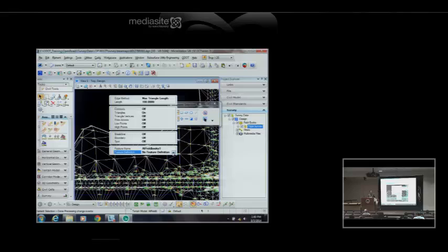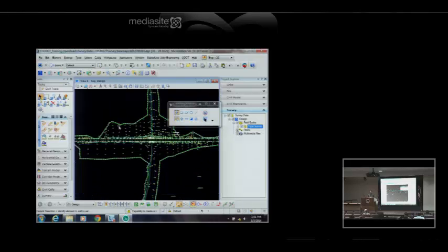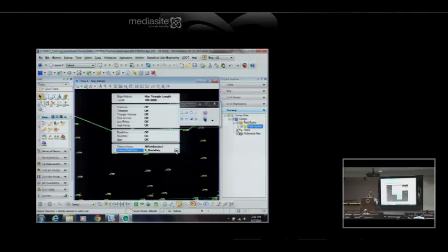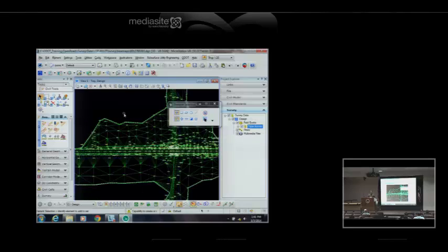Okay, so there's some features, and when I drop down, I have some features for terrain models. So there's some existing ones. One of them is X_boundary. If I pick that, that changes the display of that terrain model to only show me the external boundary. Then there's some different ones there that I've configured. Maybe I do want the triangles, so I'll use this X_triangles. Since no feature was defined before, that's why it was all white.